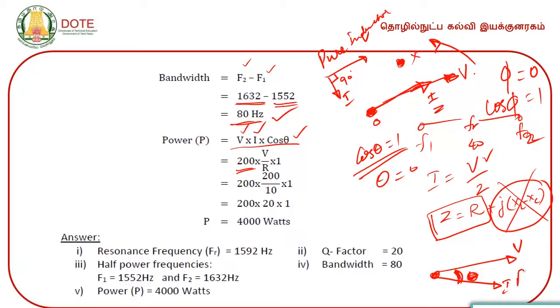So, why is the current lagging behind the voltage by a small angle which is less than 90? Due to the presence of R plus XL here. Suppose there is a presence of R and XC, then you will have voltage like this, then you will have a current. This is the total current. What I am talking about is the total current. So, this is your theta. This is the presence of R plus XC. So, the current will be leading the voltage.